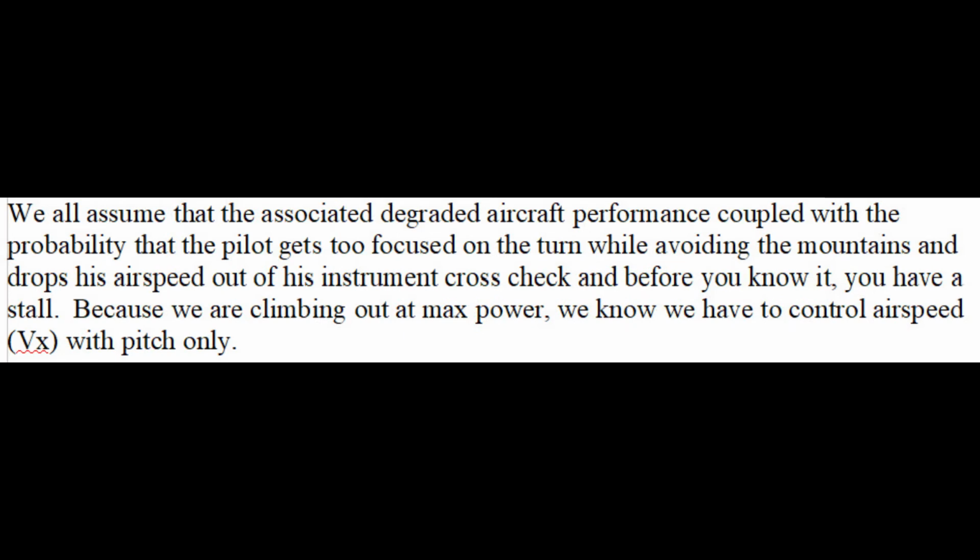We all assume that the associated degraded aircraft performance, coupled with the probability that the pilot gets too focused on the turn while avoiding the mountains and drops his airspeed out of his instrument cross-check, and before you know it, you have a stall. Because we're climbing out at max power, we also know we have to control airspeed in the climb with pitch only.